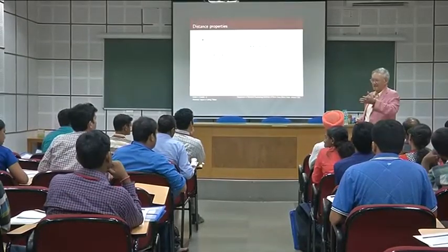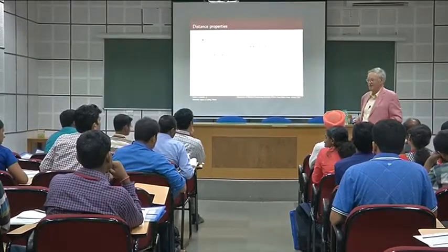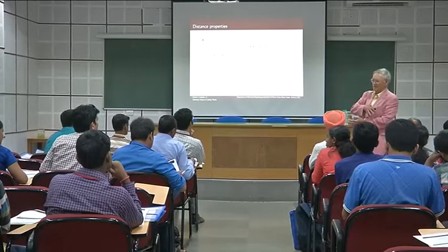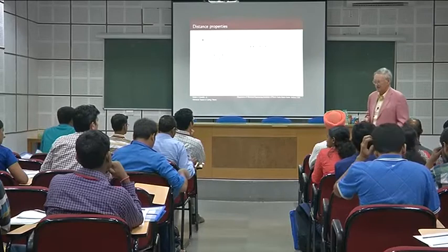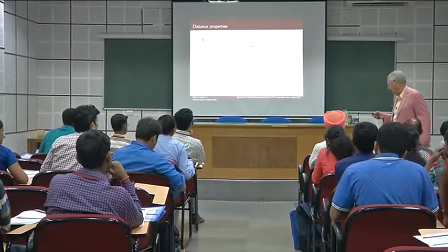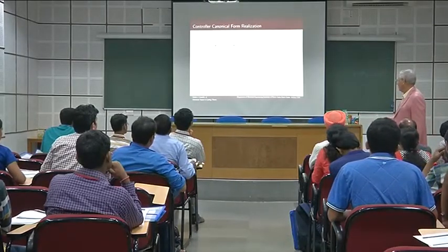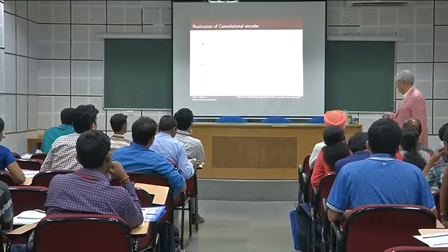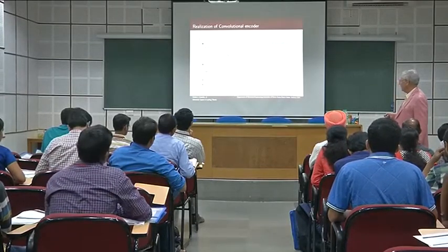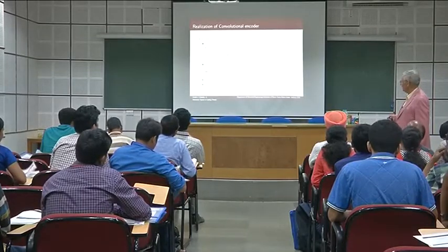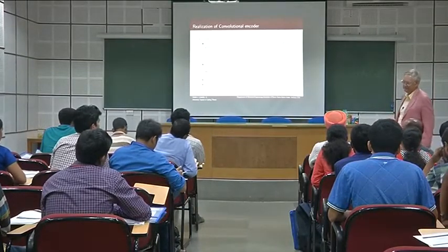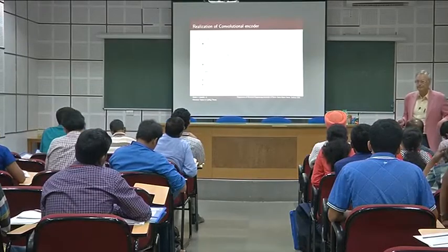It's analogous to what you do with the block codes. Once you get it in systematic form, you can convert. With the block codes, you take the transpose of the parity part, and that's actually what you do here too. This is the parity check part of the generator matrix, and you take the transpose of that and put it here. So that's it.